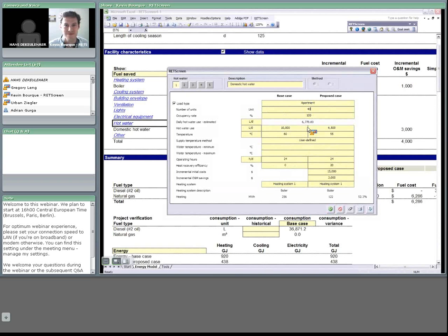Well, actually, in my building, there's a lot of young families, and I know there's a lot of kids in the building. So I think it's probably closer to 10,000 liters per day in my 40-unit apartment building. Now, I was going to implement flow reductors at 35%. So 35% reduction from 10,000 is 6,500. So this is the proposed case. Base case 10,000, and I'm proposing to put it at 6,500. The temperature right now is very hot, and I'm proposing to reduce that temperature by 5 degrees.